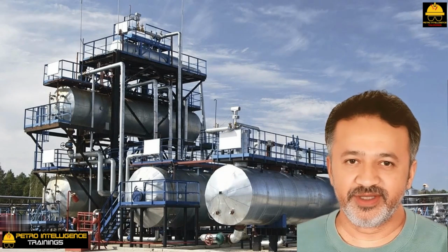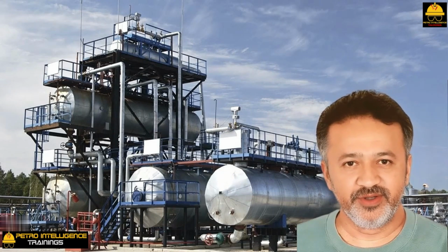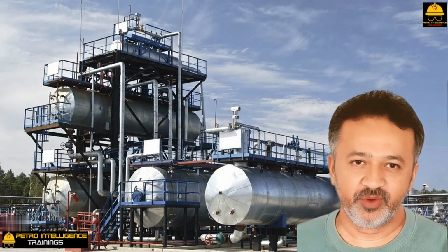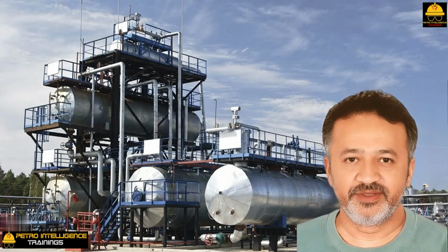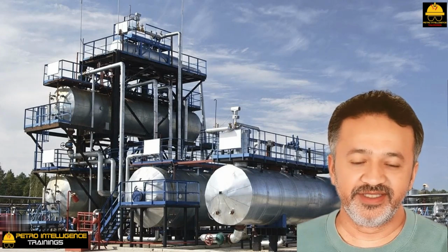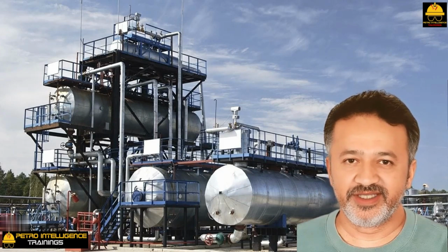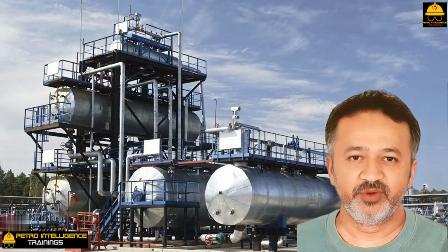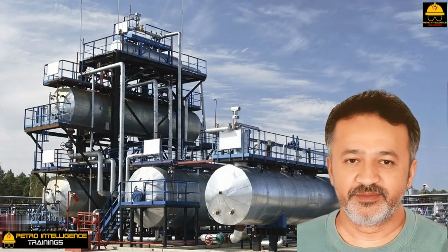But, more importantly, from an operator's point of view, the silicate deposits eventually break from the blades. This unbalances the rotor. An unbalanced rotor is the fundamental cause of vibration. Vibrations lead to damage of the shaft bearings and seals. Eventually, vibrations will destroy the turbine's internal components.